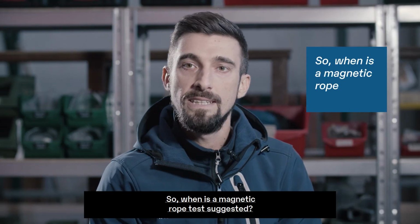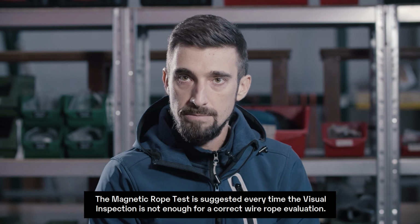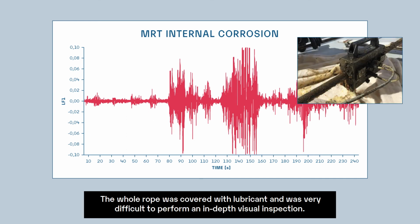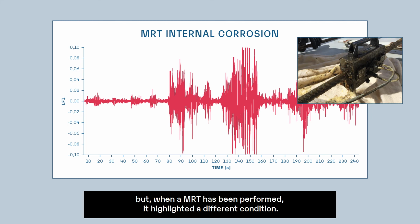So, when is a magnetic rope test suggested? A magnetic rope test is suggested every time that the visual inspection is not enough for a correct wire rope evaluation. This picture shows a diagram corresponding to a magnetic rope test in a marine environment. The whole rope was covered with lubricant and it was very difficult to perform an in-depth visual inspection. The inspector did not find any problem, and the rope was declared in good condition. But when a magnetic rope test was performed, it highlighted a different condition.